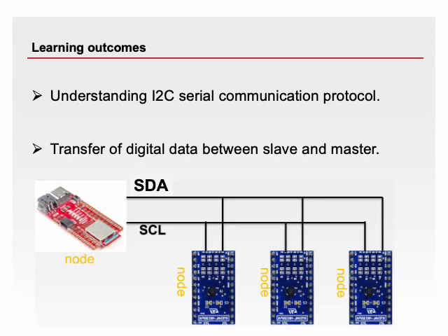In this video, I explain the I2C protocol used in serial communication for just a master and a slave, while the protocol supports multi-master and multi-slave communications using just 2 wires. This protocol supports different features and offers a simple and efficient way to interconnect devices while using minimal I/O pins. Let's dive into this protocol that I used to interconnect breadboard Artemis Nano with a 6 degree of freedom inertial motion unit in my next video.